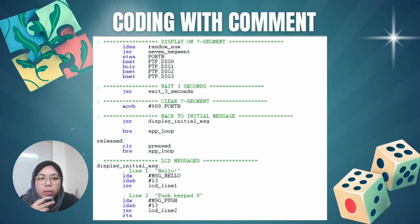Next, the output and reset process. Display the random number on the 7 segments. Hold the output for 3 seconds. Then clear the display and reset the system, showing the instruction message on the LCD. After generating the random number, the system displays it on the 7-segment display for 3 seconds. The display is then cleared. The LCD shows the initial instruction message again, and the system returns to idle mode waiting for the next key press.